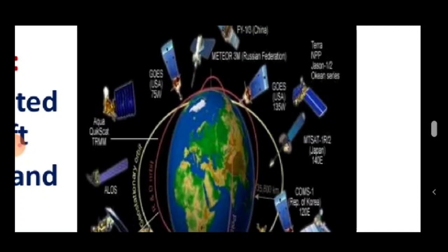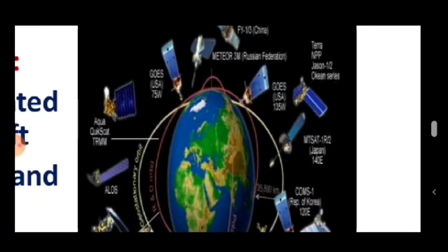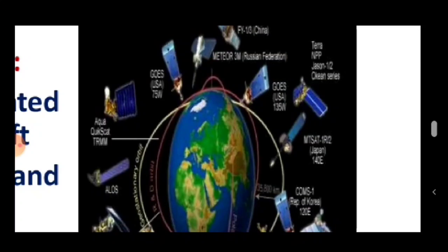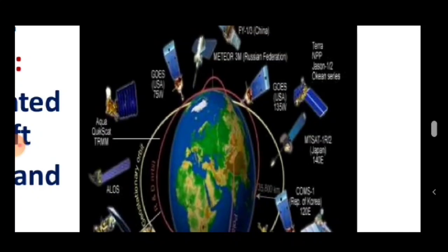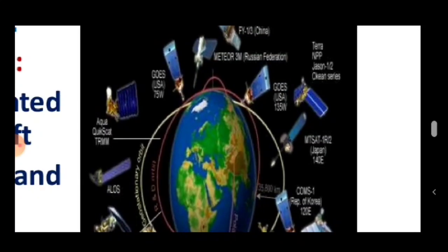And Landsat 4 and 5 are more refined. They have more refined multispectral scanners, used with a thematic mapper on board, with band 6 resolution of 30 meters and thermal IR resolution of 120 meters, and 7 wavelength bands included.